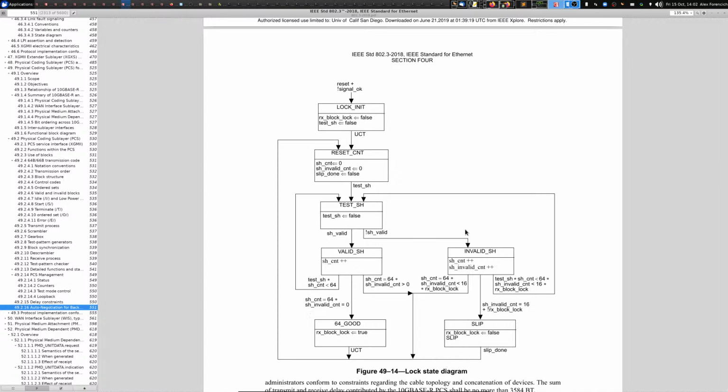But on some of the Intel devices, the bit slip is actually done on the other side of EMIB on the tile. So as a result, it takes a long time to do the bit slip, like 100 nanoseconds or something like that for each bit slip. I actually can't remember the numbers off the top of my head, but it takes many clock cycles, and as a result, it takes a lot longer to get block lock. But this is in general pretty simple because they're just trying to lock onto a 66-bit frame. When you have FEC involved, it's a different story.